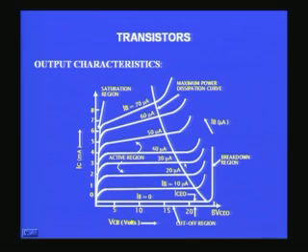It is almost flat, but as I increase the base current, you find the slope slightly changes from being purely horizontal. Okay, this also can be understood. Now, therefore, you find there is a saturation region and there is a cutoff region, and the rest of the region in between this maximum dissipation curve and the saturation and cutoff region, what you have is called the active